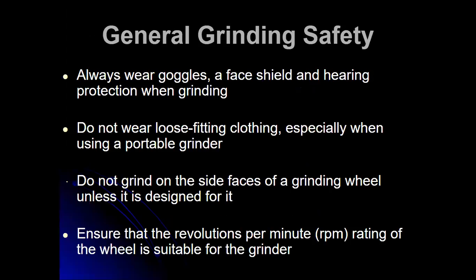So general grinding safety is always wear goggles and a face shield and hearing protection while grinding. So safety glasses, non-negotiable. It is a must always in the shop whenever there is even one single power tool on. Even when we're using hand tools, we're using hammers, files, hacksaws, safety glasses. I don't want that stuff in your eyes.